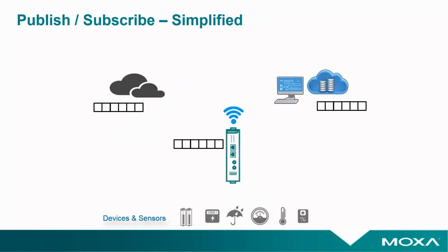However, the way modern IT systems, like the web work, uses a different architecture. This is publish-subscribe. In this architecture, any number of devices or subscribers can connect to a server or publisher, and data changes are communicated simply by having the publisher update the data. This architecture allows for much broader scalability as the subscribers expand without impacting the configuration or purpose of the publisher. You can also scale the number of servers or publishers and have different subscribers connect to different sets of servers.